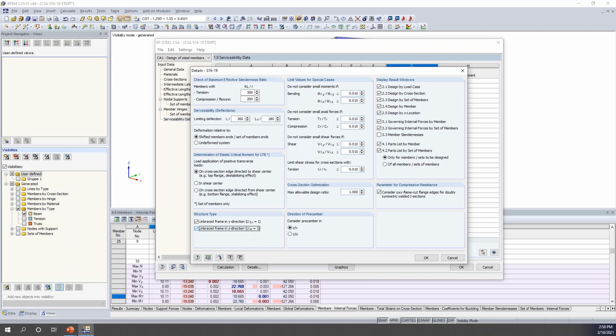There are also some other requirements within the code that if we're using the simplified stability method, forget Annex O, you also can set this use of one factor equal to 1.0 for unbraced frames, again, according to clause 13.8. So just something to keep in mind. But remember, we are taking into consideration P little delta. We are designing according to Annex O.2 stability requirements, so we can leave this option checked.